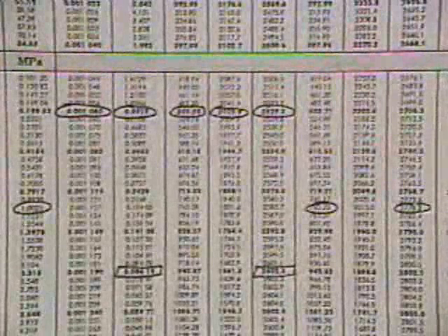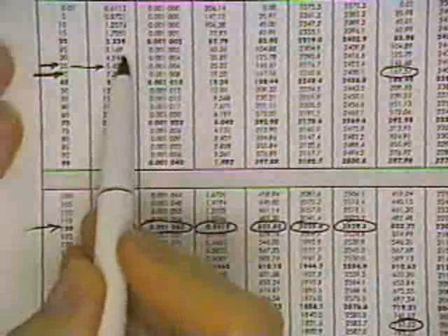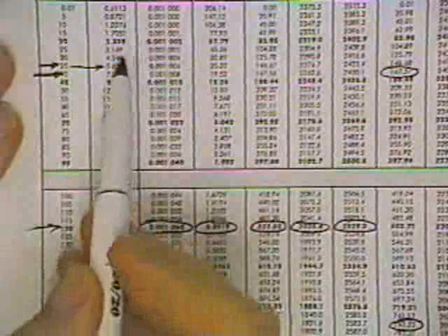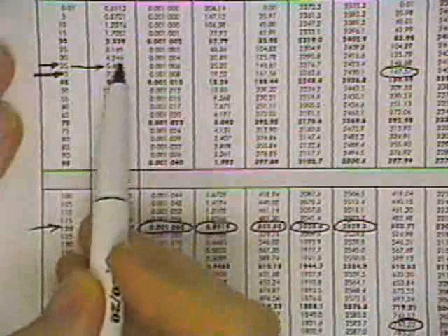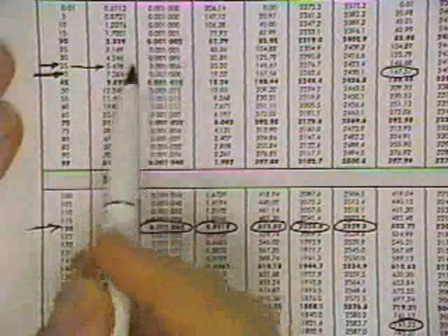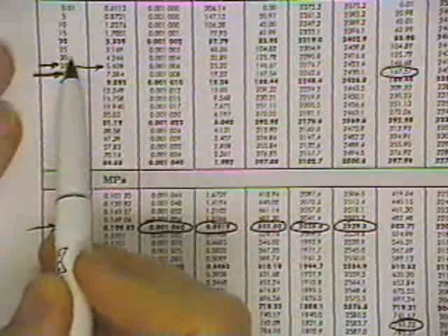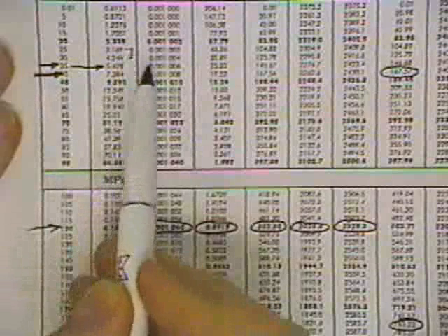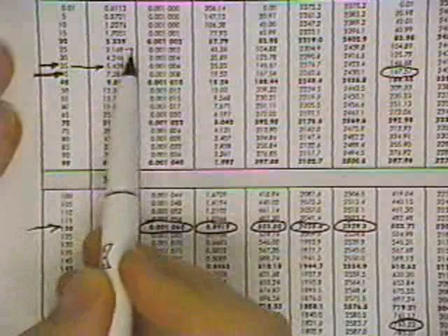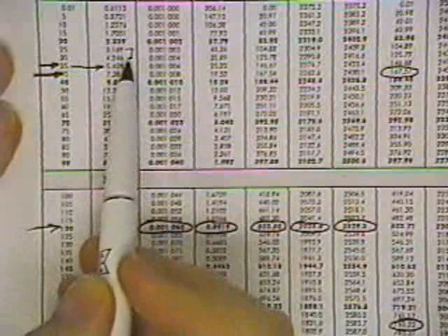Okay, so we found the dew point, and we are at a pressure of 3.94. If you look up here at 3.94, you're going to see that we've got a 3.169 and a 4.246, and so this is going to be one of those little nasty interpolation problems. But you can see that the dew point temperature is going to lie between 25 degrees centigrade and 30 degrees centigrade, and you're going to have to linearly interpolate to find the value of the temperature corresponding to 3.94 kilopascals. And so I've done that.